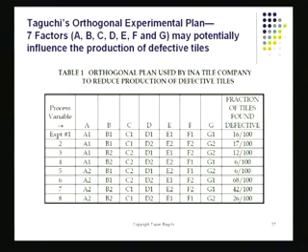So what they tried to do was, they said, well, is there some way by which we could optimize the settings for these factors? And they identified, by brainstorming, they were able to identify 7 different factors. At that time, Taguchi heard about this problem, and he became involved, and he started to advise them. And what Taguchi did was he set up a simple orthogonal array, and I'm showing that on the screen here.